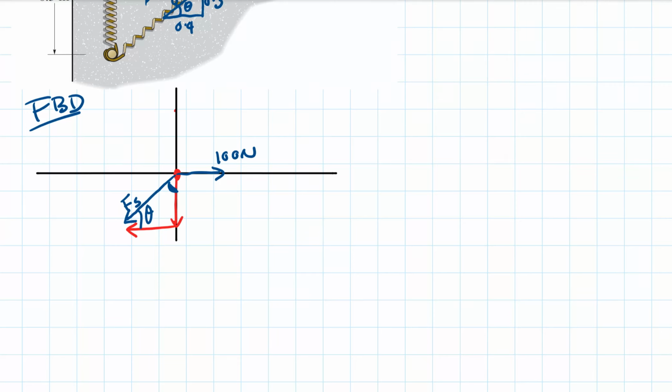All right, and here obviously we have the weight due to gravity, and we have the normal, but here we will not add the forces in the y direction because there is no movement in the y direction. And there is no friction because we're told that we have a smooth surface, and friction is related to the normal force. So here we will say that the sum of the forces in the x direction equals mass times acceleration in the x direction.